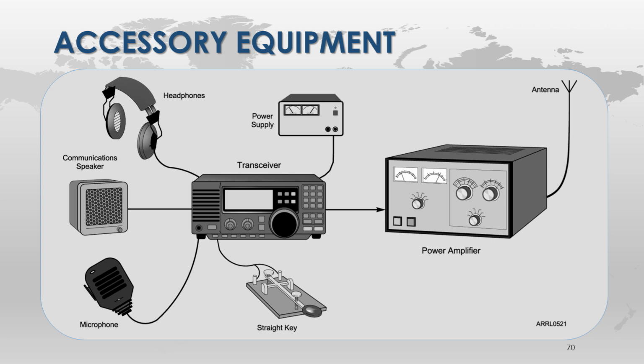You've got transistorized amplifiers that run off 12 volts DC, 13.8. They still take up a lot of amperage, so you're going to use some big batteries. Then you've got tube amplifiers that run high voltage, and you can run them off 220 or 120 volts. Yeah, it just depends on the amplifier.